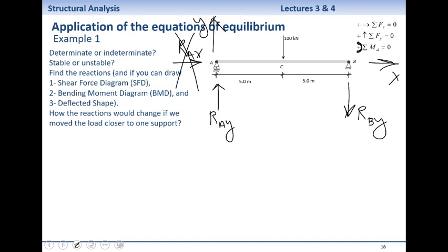Now, at point B, can we have a horizontal resistance? Yes, because it's a pin. Fantastic. Okay. I just assume there is a force going in that direction. Potentially RBX. Now, any of the two supports that we have, can they produce a resisting moment?